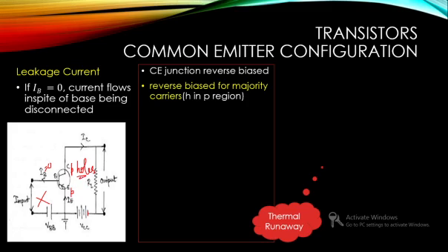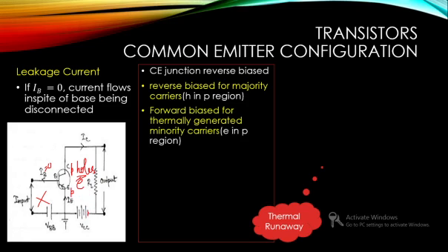But for the P-type region, in addition to the majority carriers, it has minority carriers. What is the minority carrier in P region? Electrons. So electrons are connected to the negative terminal. So they are connected to the same polarity. So what do minority carriers feel? Minority carriers feel that they are connected to the same polarity, which means they are forward biased.